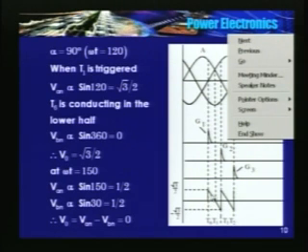For other loads, you cannot have continuous conduction for alpha equal to 90. Even if the load is of RLE type, I into R is always positive, E is positive. Average value across the inductor is 0, so Ri plus E should be 0, it's just not possible. So load current can be continuous for alpha equal to 90 only for an inductive load, purely L load. Okay. Last case, I will just increase alpha to 120.